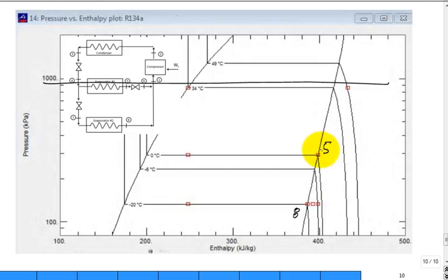We go to an expansion valve. The expansion valve is isenthalpic, straight down, isn't it? So it's almost easier to find your states because you're having a lot of expansion valves and things are constant pressure. pH diagrams, they like for refrigeration.